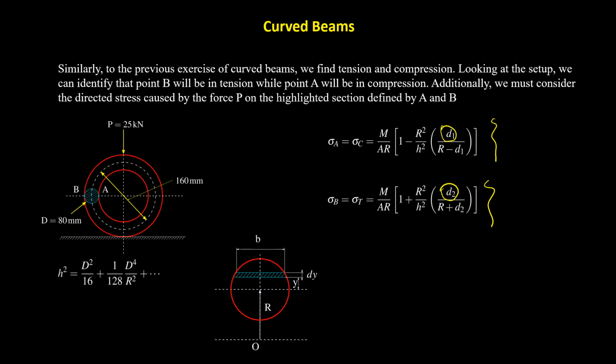Now the section parameter is a function of the diameter of the section of the part, and also a function of the radius of curvature, which we don't have at the moment. We have the diameter of the whole ring. However, that diameter is not the radius of curvature. Let's get rid of the area because that's an easy one. And then let's come back again to the radius of curvature.